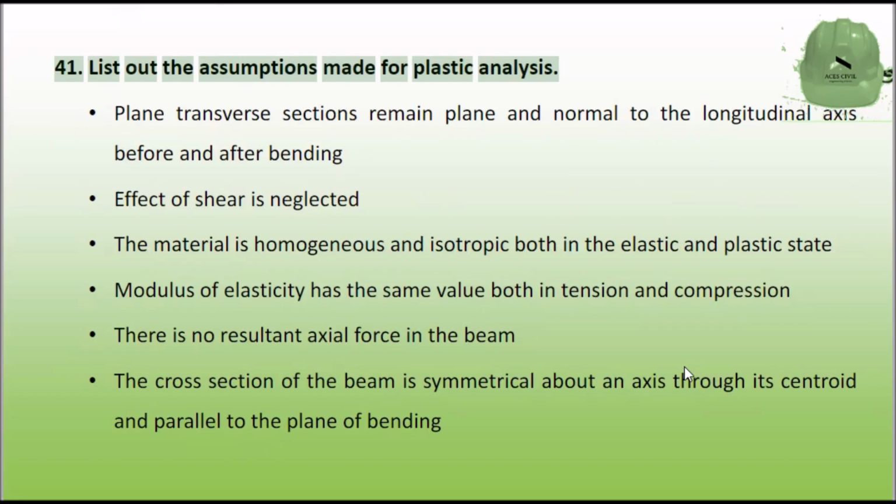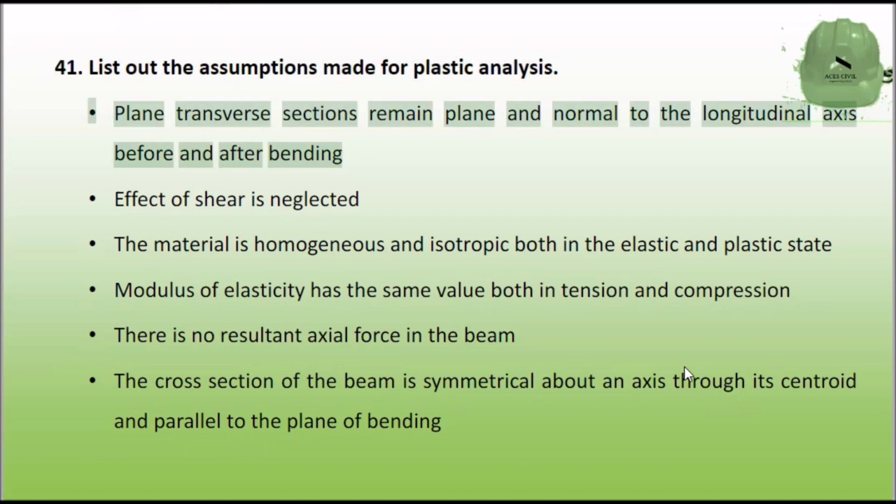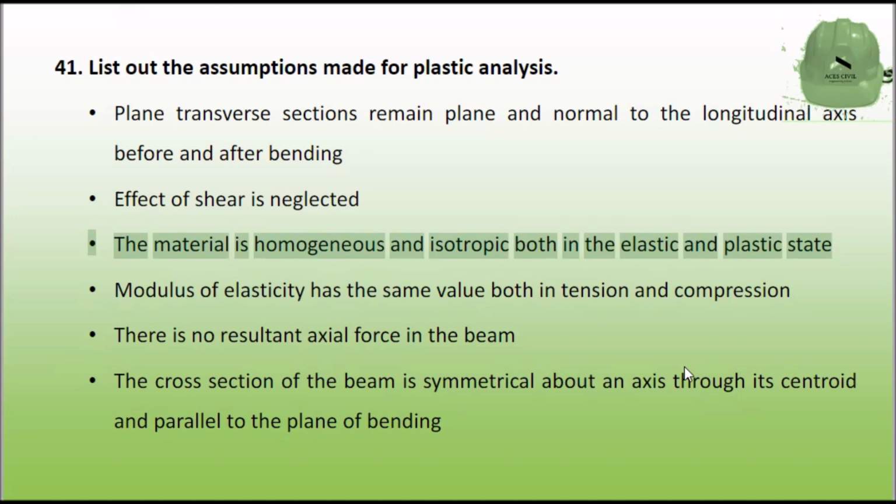List out the assumptions made for plastic analysis. Plane transverse sections remain plane and normal to the longitudinal axis before and after bending. Effect of shear is neglected. The material is homogeneous and isotropic both in the elastic and plastic state.